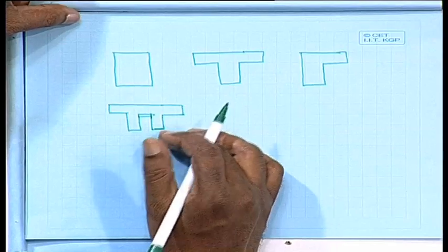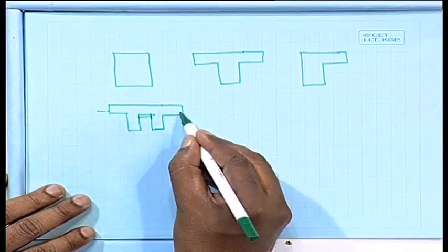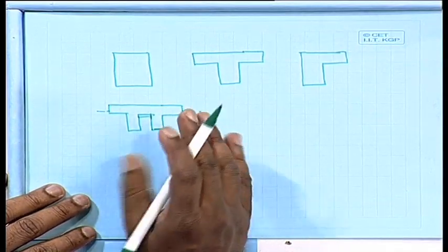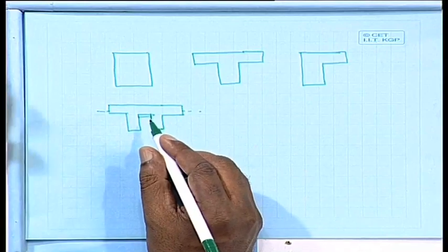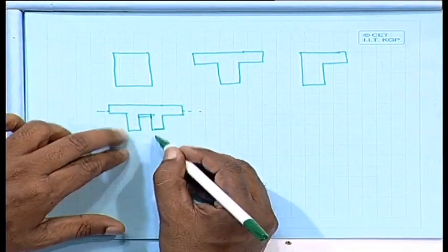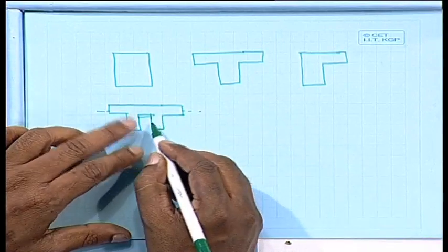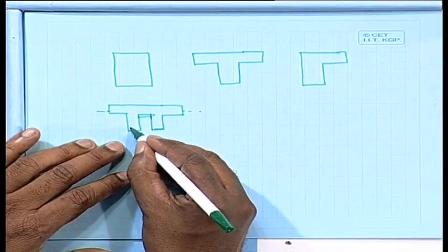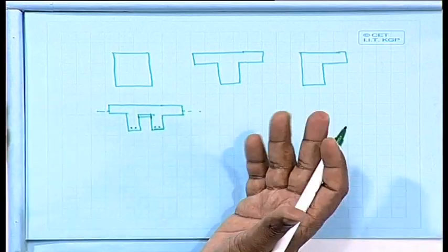Here again it is nothing but the T section, because if the neutral axis can be provided within the flange, then there is no problem, because then it is just a simple rectangular one only, and the other part, the concrete, is not taking any load or moment. Whatever reinforcement you are providing here is the area of steel.